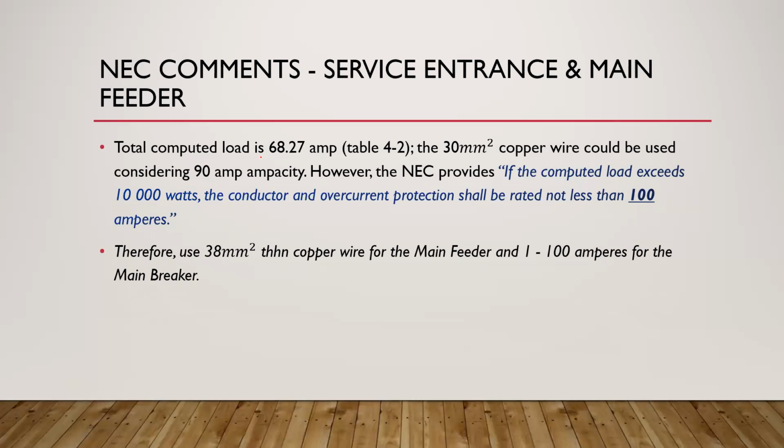So yung copper wire size is 30 mm squared. However, the NEC provides that if the computed load exceeds 10,000 watts, the conductor and overcurrent protection shall be rated not less than 100 amperes. So yan ang reason why. Therefore, we will use a 38 mm squared conductor wire for the main feeder and 100 amperes for the main breaker.